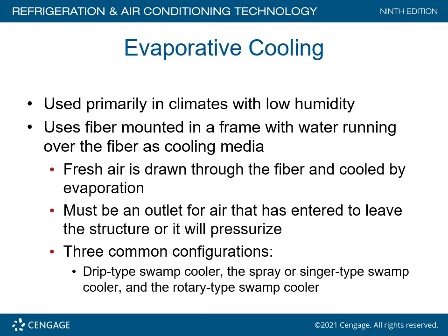Normally, if you were to do a humidity check outside, you would find the humidity, especially on a day like today, as an example, I see thunderheads developing to the east of me in Riverside as we speak. And I would venture to say probably later this afternoon, the relative humidity might reach 45–50%. Obviously, if it goes to 80–90, that means it's raining. Simple as that. But getting back to evaporative cooling, low humidity is key there. If you have a dry climate such as Phoenix, Arizona, Indio, California, or Palm Springs, it would work.